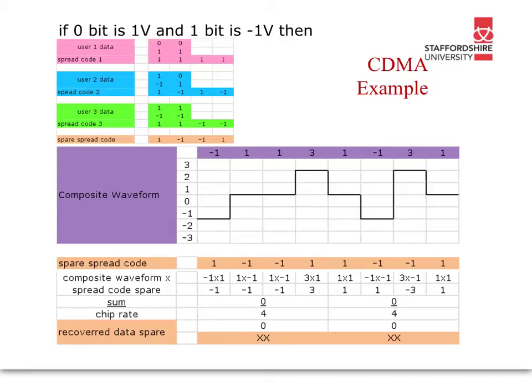The reason we get 0 here is because we used the Hadamard or the orthogonal codes, and also no noise was added. If there was some noise, or if they were semi-orthogonal or random, then we would get some small random noise appearing here. However, we would still not be able to determine whether a 0 or a 1 was transmitted, and that doesn't actually matter. But basically what I'm saying is if you're not in possession of a valid code, then you're not able to decode what was transmitted. That's the main point of what I'm saying.